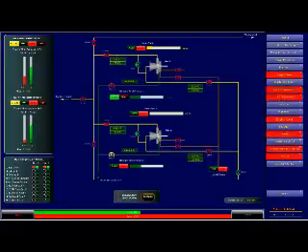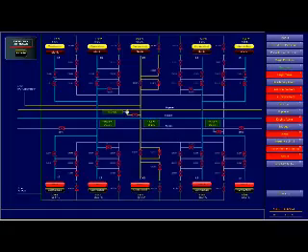But let's say we are connected to the shore, and the shore connection of vapor has already been connected to us. Lines we have cooled down earlier already, so our lines have got frost on them, and they are at minus temperature. Of course, the more we delay it, it could even go to plus, so let's start the operation ASAP. But of course, our usual checks need to be there.